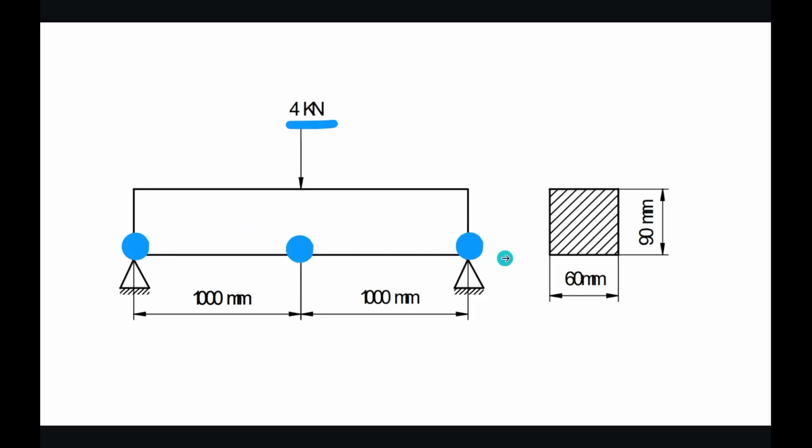So these are the points and we'll be connecting them, then proceeding with the meshing and assigning loads as per the hinges and with the force acting along the downward direction of vertical support. So this is the cross section values we are given. So let's start the structural part in the ANSYS.